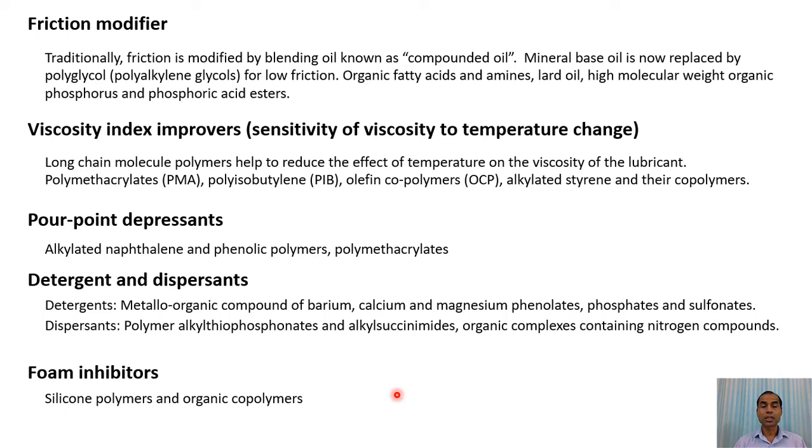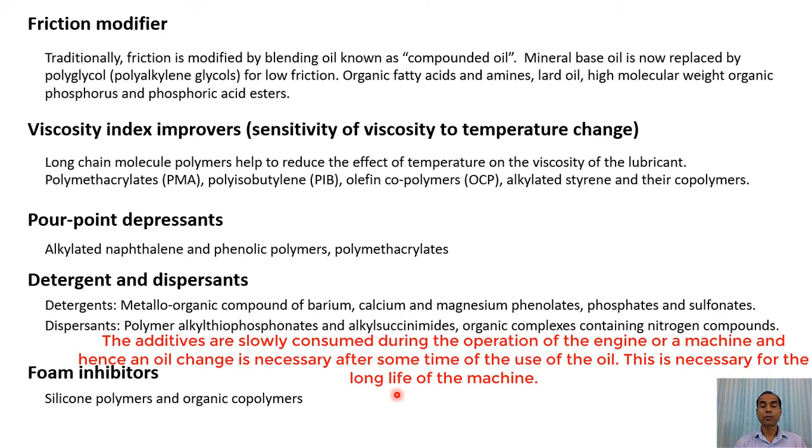What is important is with time these additives can get depleted because these additives are used up during the performance of engine or any kind of machine. So therefore at some point the additive package can become almost completely depleted, and in that case it is necessary that we do the oil change.